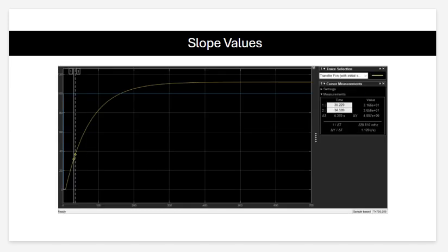This right here is our slope values. To tune the controller, I needed the slope of the response curve. Using 2 points on the graph, I calculated the change in output and the change in time, which gives us this line slope. This slope is crucial because it becomes the value of m in the Ziegler-Nichols style tuning formula, so the step directly feeds into the PID gain calculation.